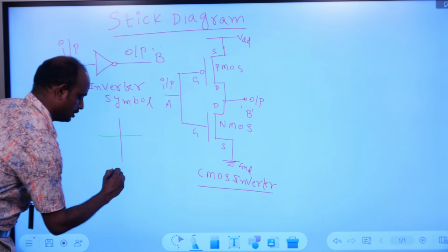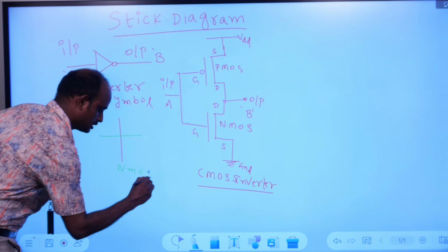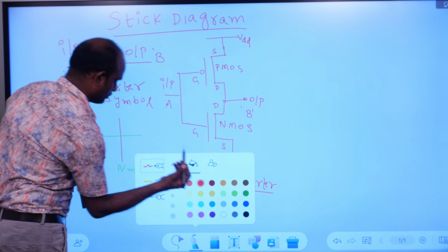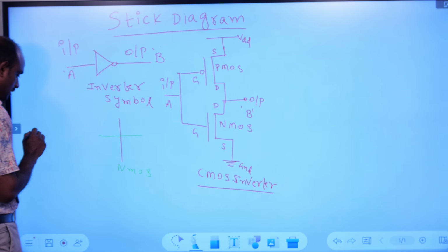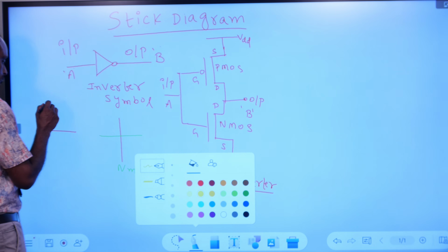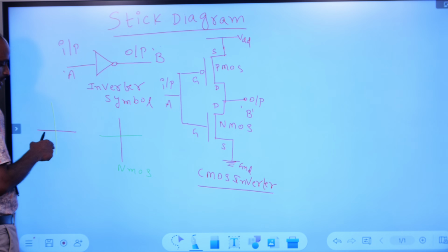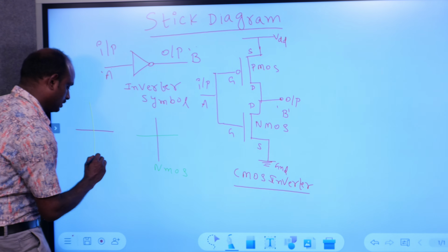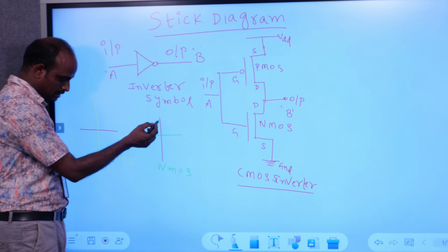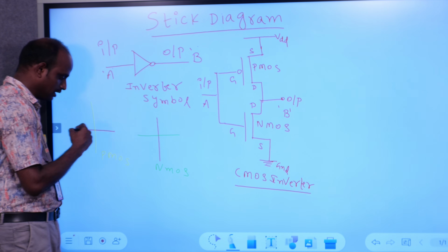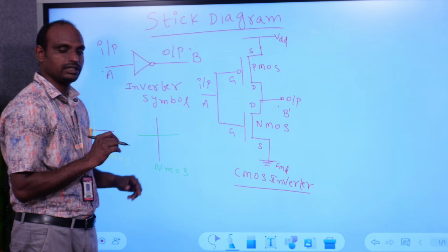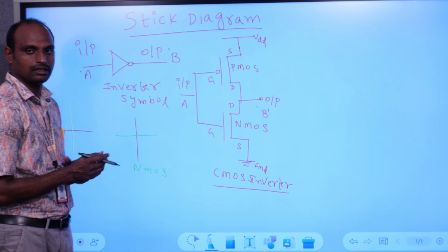So this is an NMOS transistor. If we require PMOS, we take, for example, a horizontal line for PMOS, and vertical we require yellow. So P diffusion is crossed with polysilicon. So this is PMOS. You can observe here polysilicon I have taken as a vertical line, here I have taken the horizontal line. Anyway, you can use either; when polysilicon and diffusion are crossed with each other, a transistor is formed. So these are the two different layers.